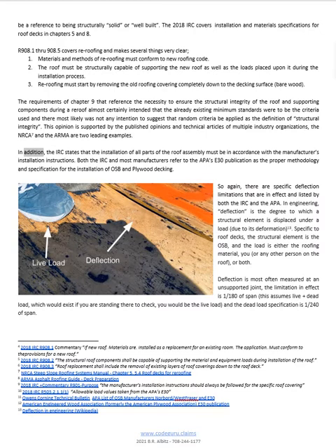In addition, the IRC states that the installation of all parts of the roof assembly must be in accordance with the manufacturer's installation instructions. Both the IRC and most manufacturers refer to the APA's E30 publication as the proper methodology and specification for the installation of OSB and plywood decking. So again, there are specific deflection limitations that are in effect and listed by both the IRC and the APA.